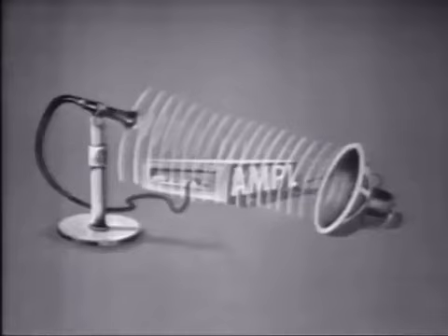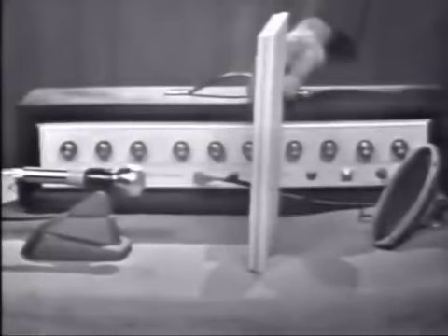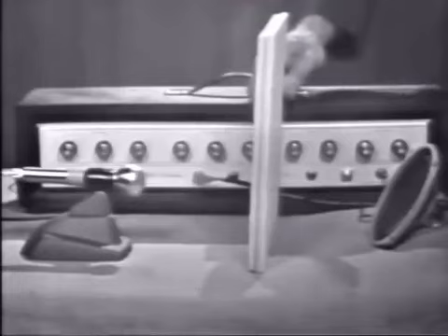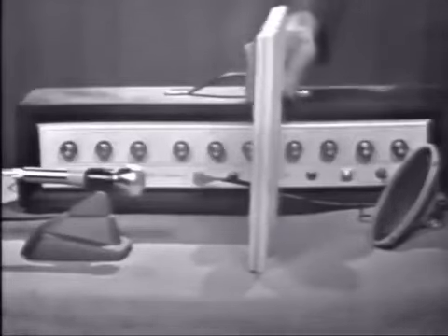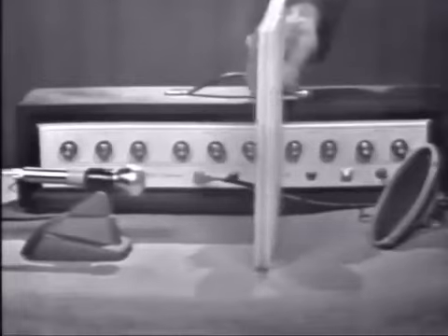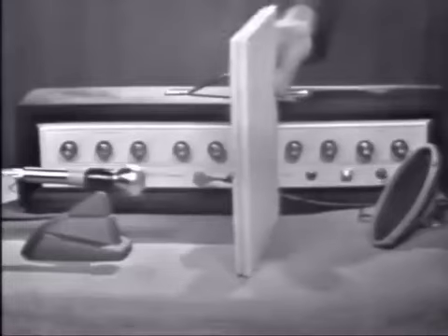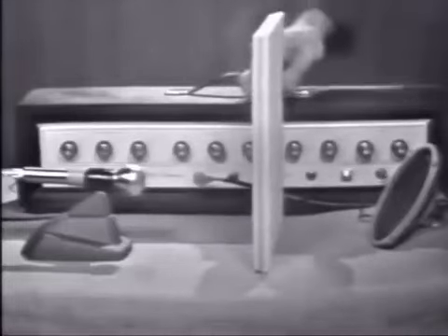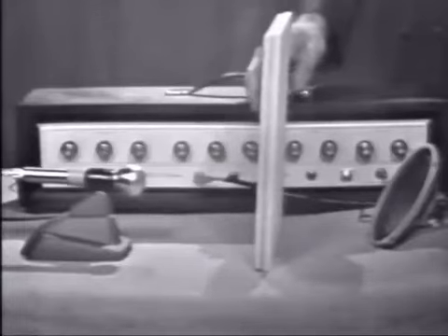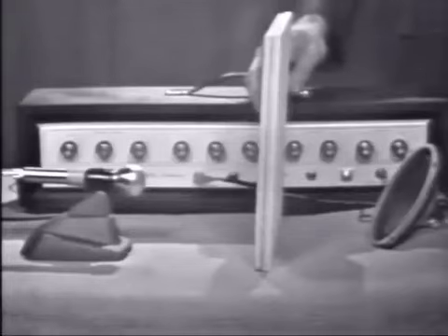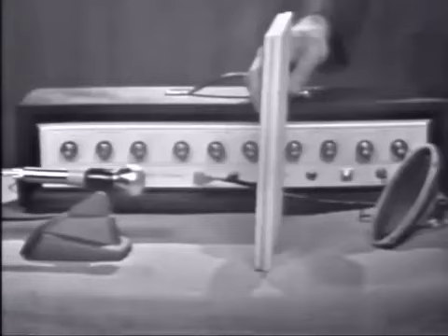stage oscillates. Now, since there's no way to control the amount of feedback, the strength of the oscillator signal continues to increase. You can hear this increase when we remove the tiles slowly and allow the microphone to pick up the speaker's output. The squeal builds from a relatively low level to a very high level. And if allowed to continue, very high oscillating currents are built up that may damage circuit components. For this reason, the amount of feedback must be controlled in an oscillator. The correct amount is just enough to overcome the losses in the circuit.